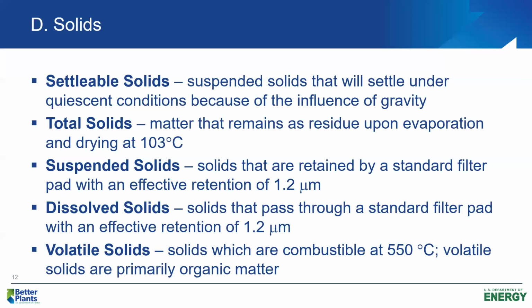And then the volatile portion of the solid is a rough estimate of the organic matter. And we determine volatile solids by combusting the sample at 550 degrees C. But ballpark estimate, again, in raw sewage, medium strength, I usually use an estimate of 200 milligrams per liter for suspended solids. And on volatile suspended solids, I would use a value of about 140 milligrams per liter.